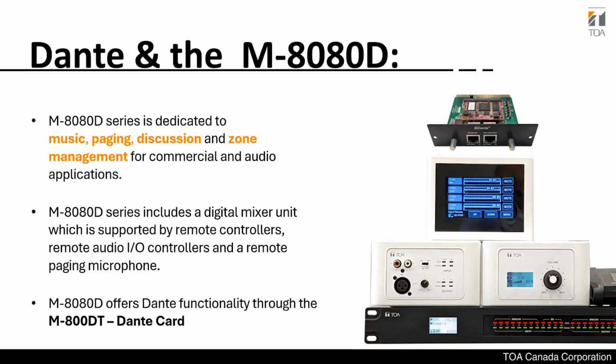Okay, let's talk about how Dante works with TOA products. As everyone knows, TOA has the M8080D series, which is dedicated to music, paging, discussions, and zone management for commercial audio, even for residential, even for small offices. So we can use this anywhere we want. The M8080D series includes the digital mixer unit, which has remote controls, volume control, including the touch panel. And there are IO boxes, to which we can send input and output devices.